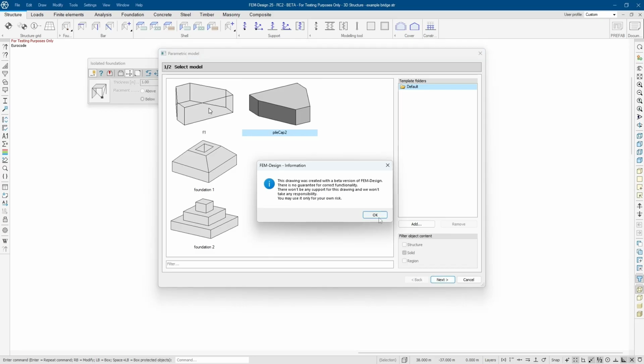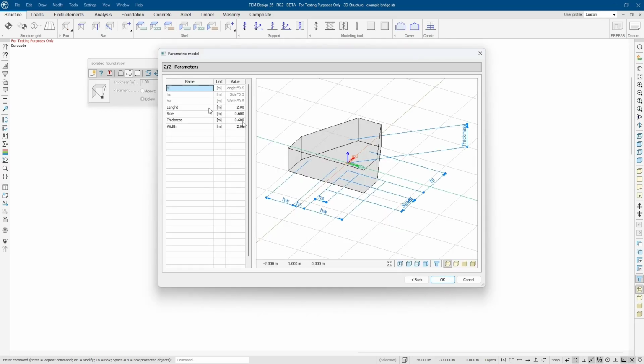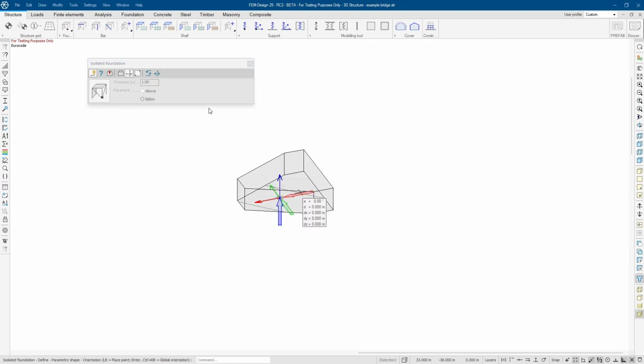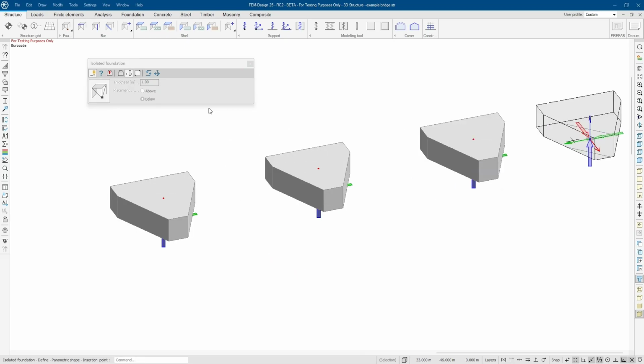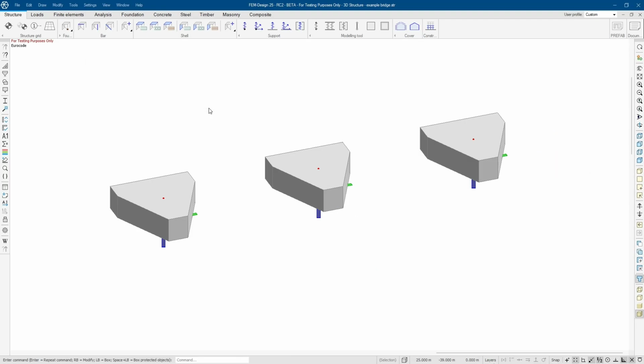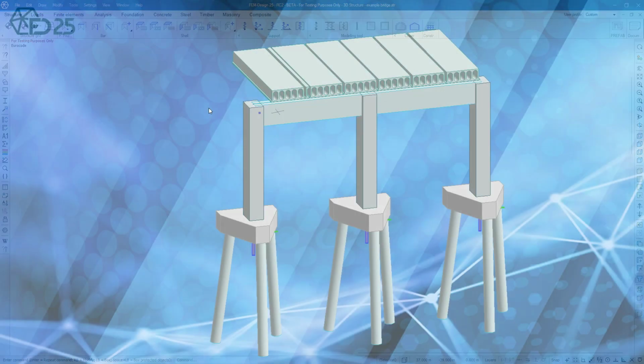But please remember that if you're using this as a pile cap, these foundations always have a spring value under them. So you have to put that as a really low number. Now you can put it here and make it really fast like pile cap shape. And it includes the supports. So if you want to add piles, of course you remove the surface support or put the low value in the bottom. And this is how you can use it.